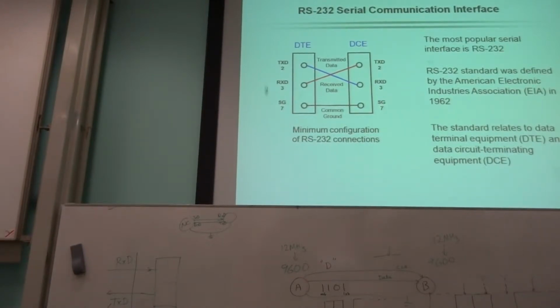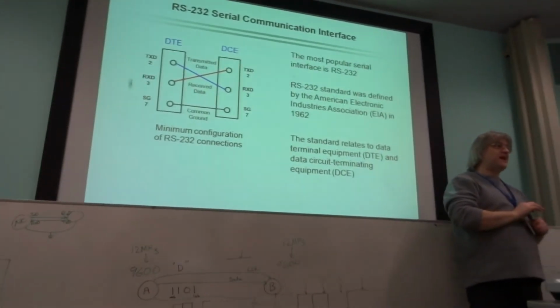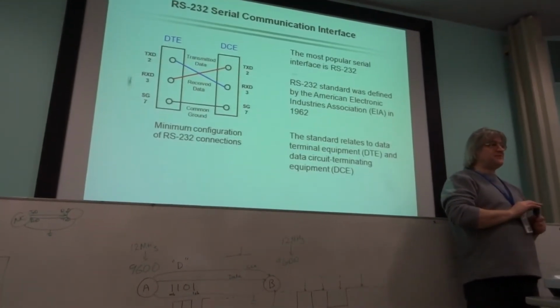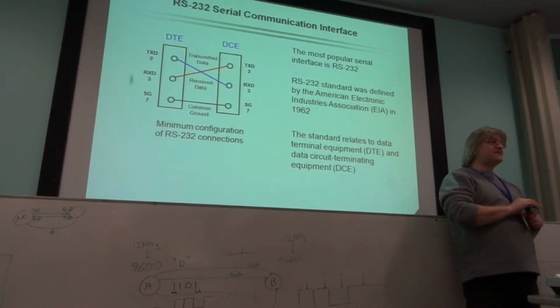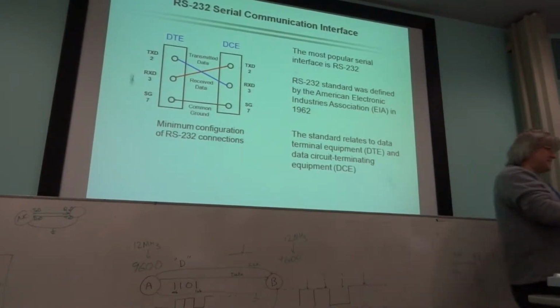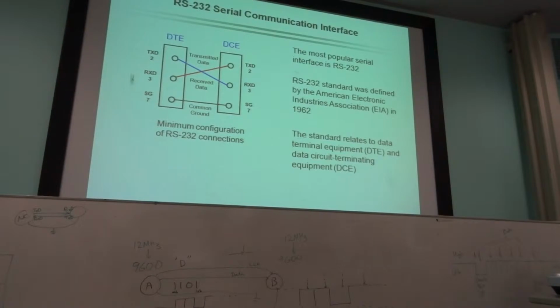If it's not compliant, how would the external chip know? It's up to you, the designer, to not plug them in. No, the external chip you get to convert. How does it know what it's converting if it's not compliant? It assumes that on one side of it you're giving it TTL signals, and on the other side it will generate things which are compliant with RS-232. If you wire it up so that, for example, on the input side it's not TTL, it's something else, it may well blow up. These things are pretty dumb, you know. That's why we have engineers.